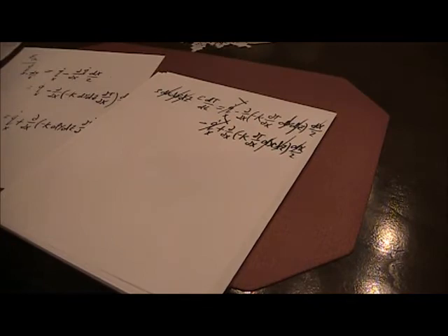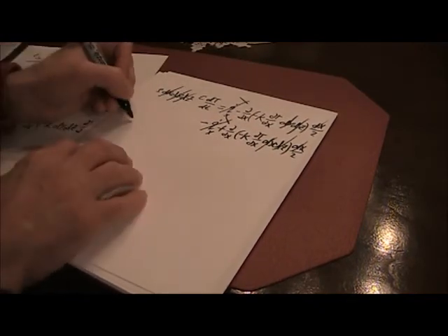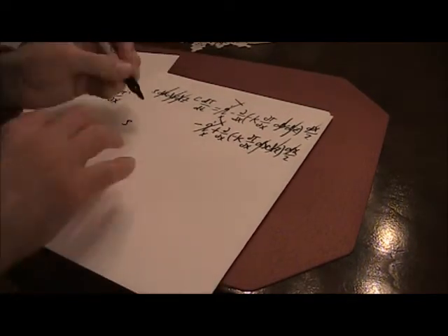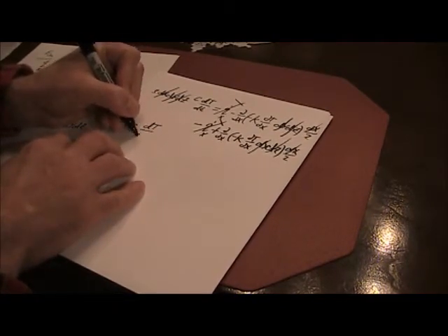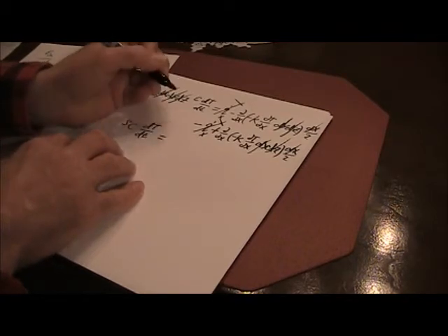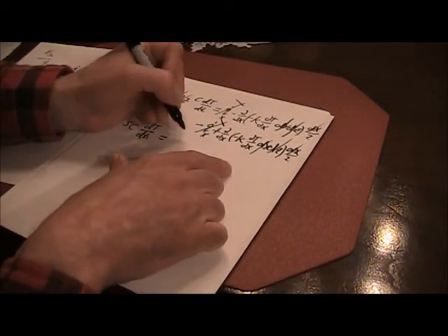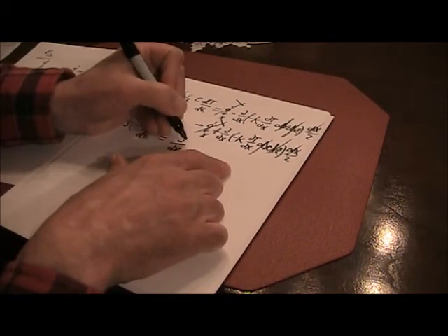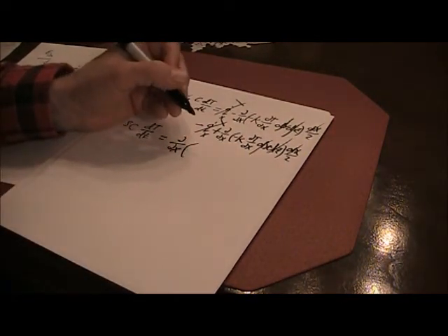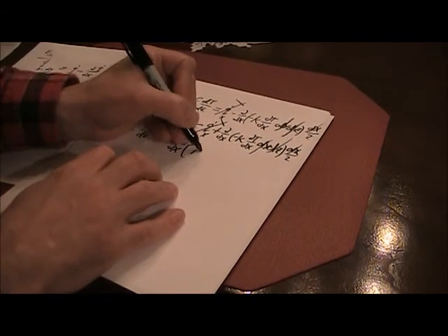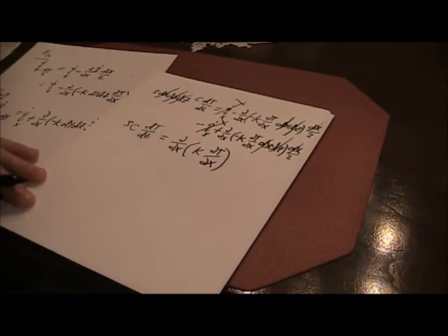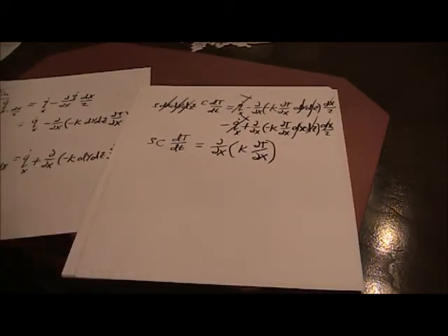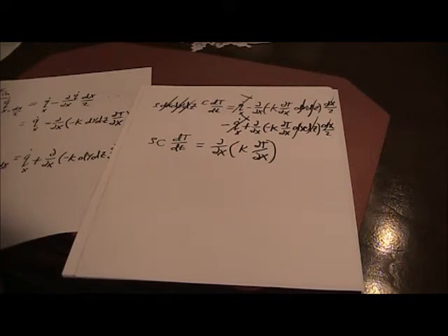So in the end, what you have left is the density times the specific heat times the change in temperature with respect to time is equal to the change with respect to x of k dT/dx. So this is the heat equation for one direction, x, one dimension.